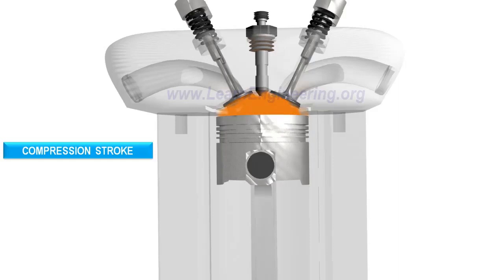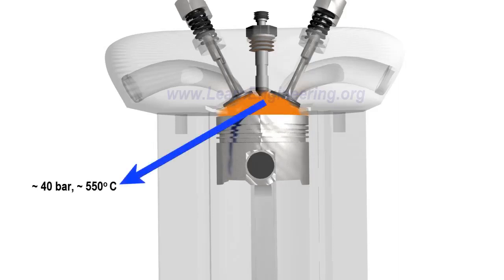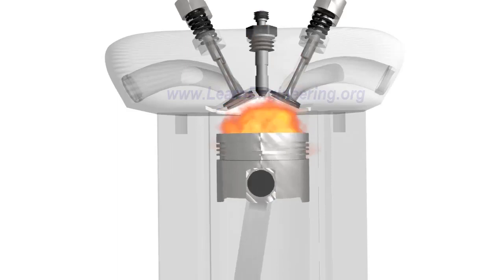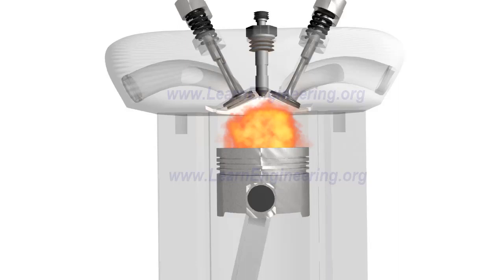During the compression stroke, the piston does work on the air, so the temperature and pressure of the air will rise to a level which is higher than the self-ignition value of the diesel. An atomized form of diesel is injected into this compressed air. The fuel gets evaporated and undergoes an uncontrolled spontaneous explosion. As a result, the pressure and temperature rise to high-level values.